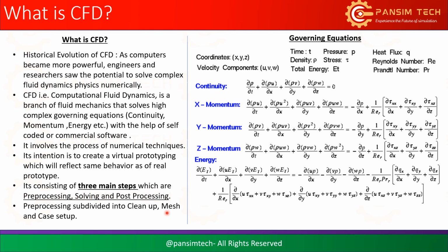If we are dividing that big control volume into small control volumes, what are we calling that? We are dividing a big domain into subdomains, and each subdomain is a discrete element. So if we connect the individual elements together, we call it a mesh. So what is a mesh? Dividing a big domain into small networks.